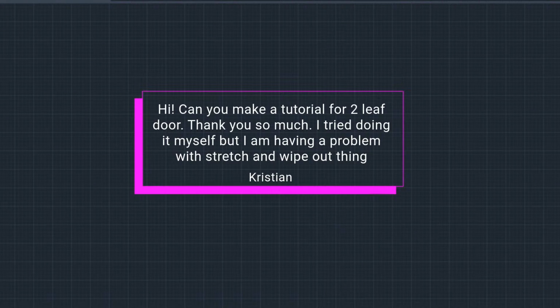If you are not seeing it, you can open it from the ribbon. And again, the linear parameter is the one that we will need first. So I'm gonna specify my linear parameter from this point, and I'm gonna go all the way up to my door width like so, and finally click like that.